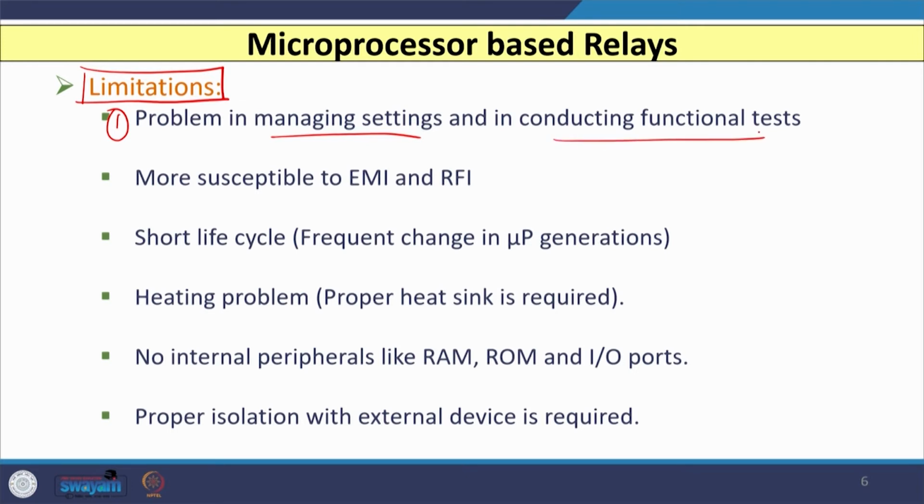Even when the testing on such type of relays is carried out, you have to, let us say, deactivate certain settings, so that proper testing can be carried out. After testing, when it is available in normal condition, whatever settings you have deactivated, you have to reactivate those settings. If you, let us say, forget by mistake, then those settings are not available for the user.